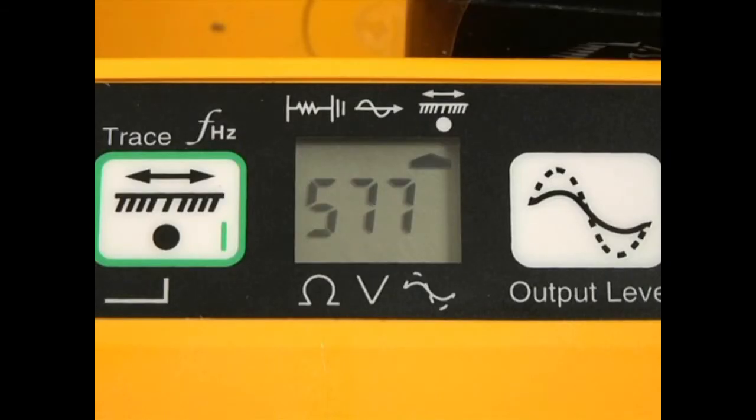When using the direct connect method, the transmitter current level will alternately flash with the selected frequency on the display. Make a mental note of the transmitter current level before you start locating the target path. To help verify the target path, compare the transmitter current level to the current measured by the receiver on a suspected target conductor.